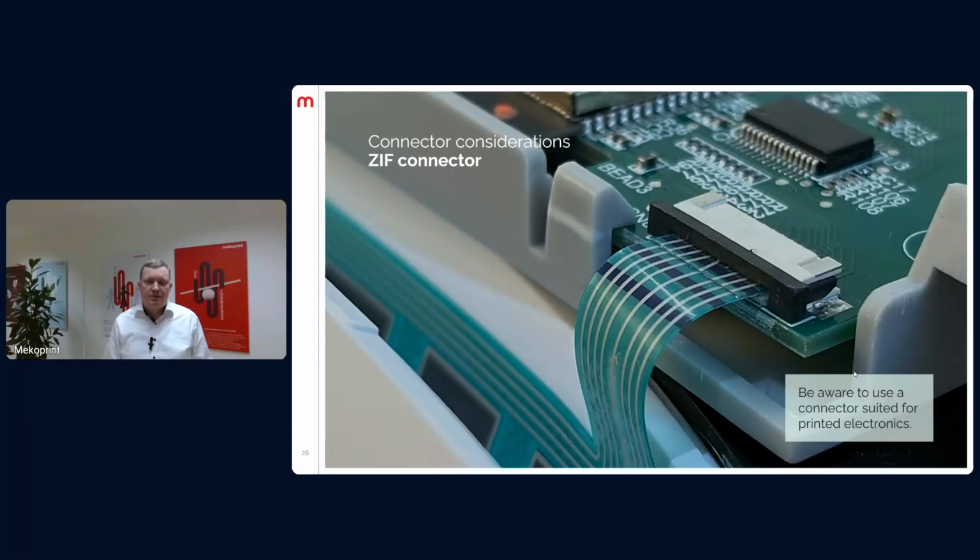For SIF connectors, it is important that the touch foil has the correct thickness in the area where it connects into the SIF connector. So this is where we are able to add additional thickness to the touch foil in that specific area with something we call a stiffener. And the stiffener can have additional functionality besides adding thickness. It can also add a small handle that you can use to insert your touch foil into your SIF connector.